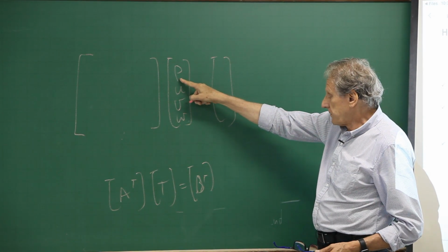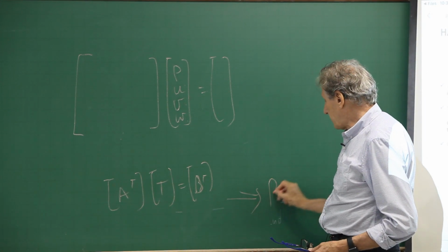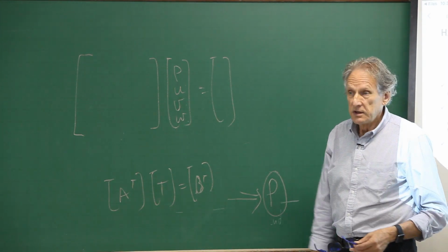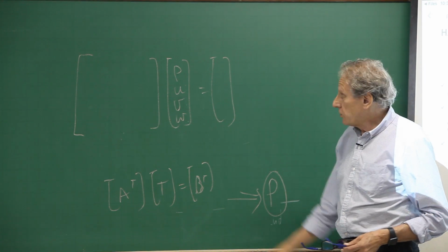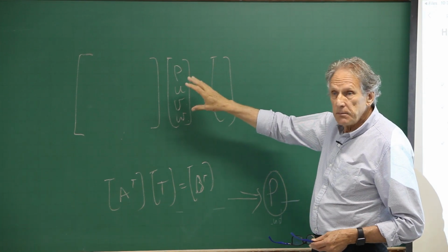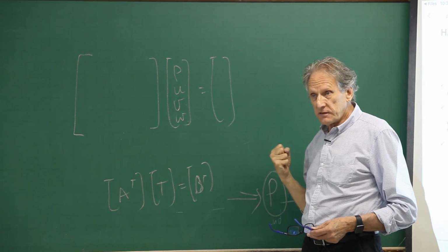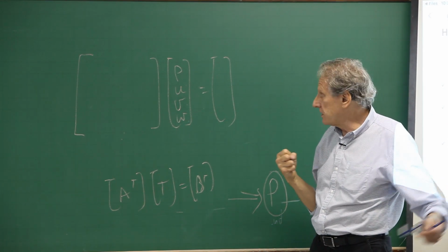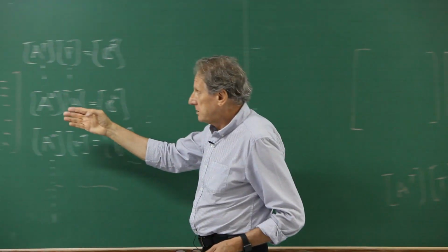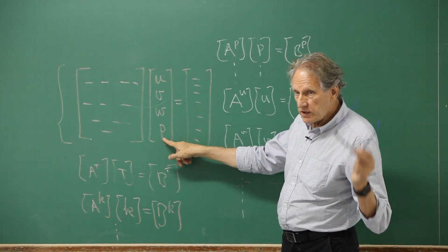Then with the density and with the temperature, you solve pressure using the state equation, because the problem is compressible flow. So simultaneously solving density-based, which means using the mass conservation equation to solve for density, this is the coupling. If it's incompressible, then you solve for pressure, but not always. I just said that.